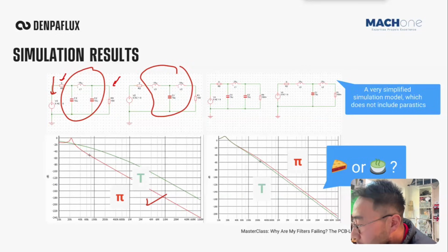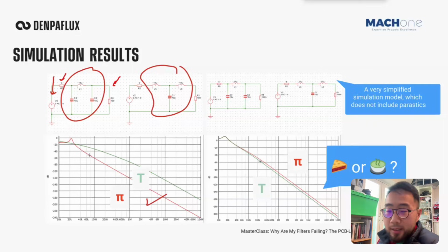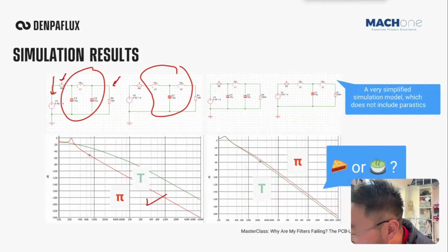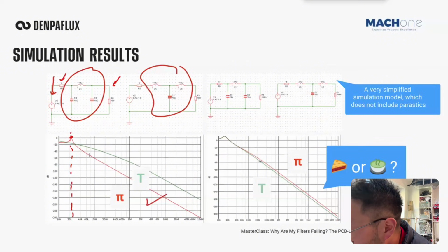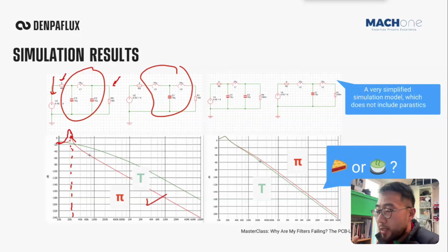And some of you may also spot, if you look at this region here, that in this case it's not bad because even in the worst case, let's say at 21 kilohertz or 22 kilohertz, you have almost no effect from this filter. But sometimes you can see in manufacturer data sheets, when they show you the insertion loss, something like this. That means this is not even filtering the noise, it's amplifying noise, okay? So that's another thing you need to know.